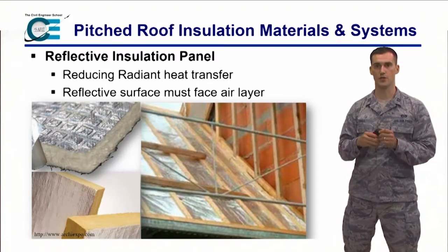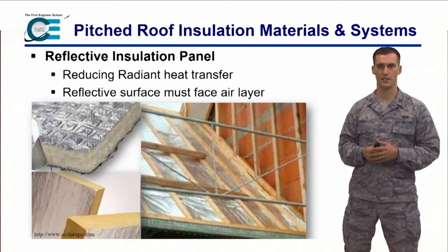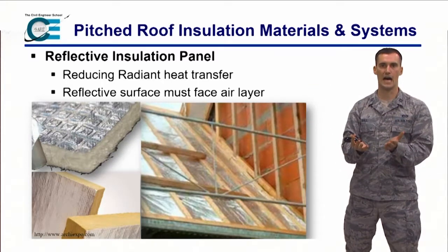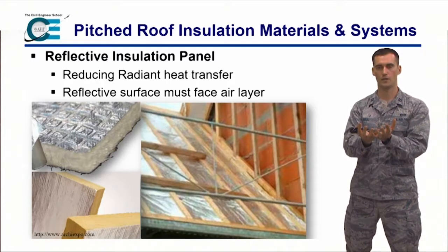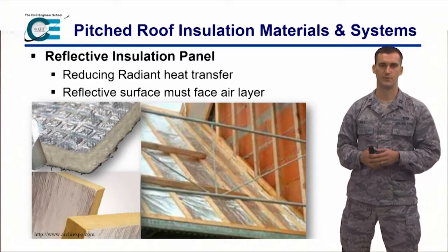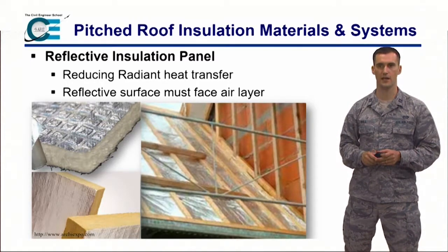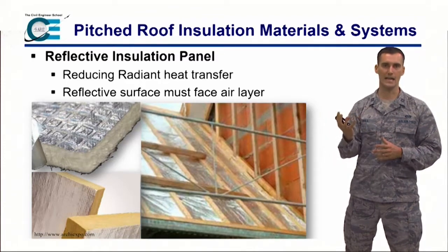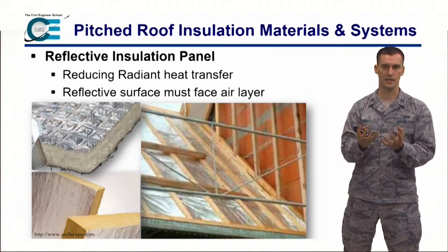If you think of your oven, the way an oven works is I make the surrounding oven all very hot. I have a cold turkey or ham or whatever it is that's in there, and energy radiates between the two. It's not heating up the air, which is then heating up the oven.